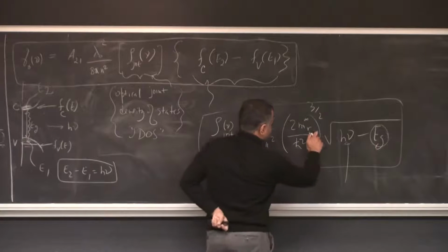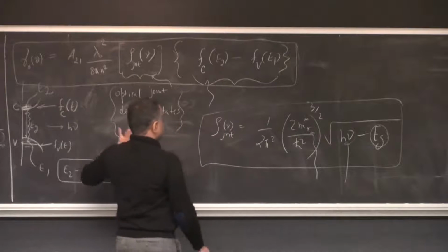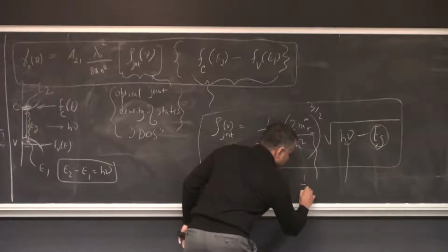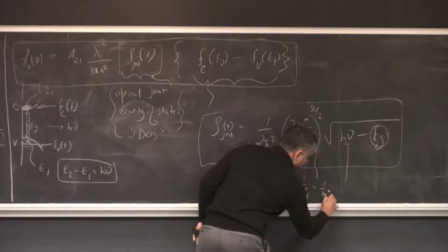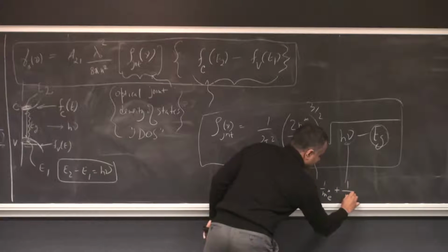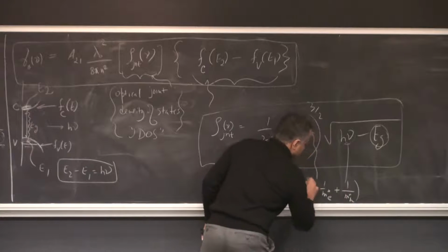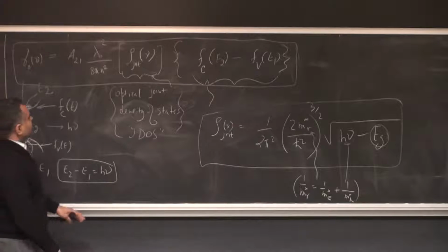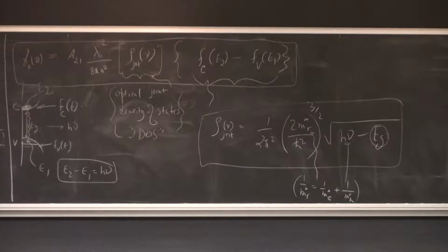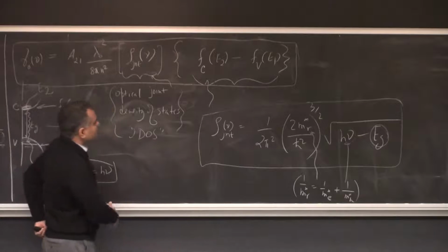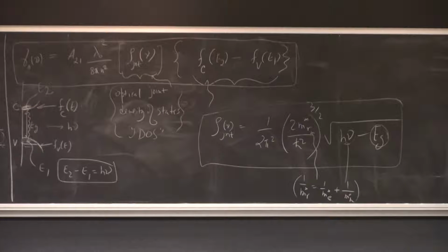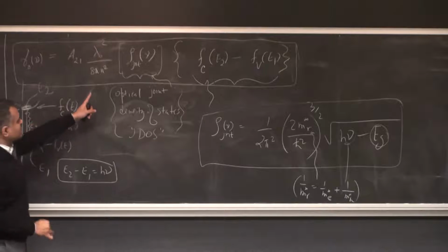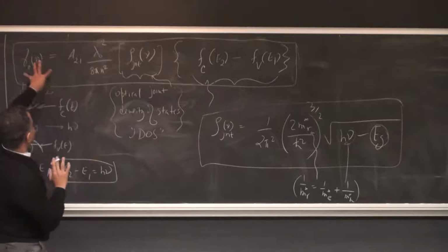There is a reduced mass. So this is a reduced effective mass, meaning the reduced mass is going to have the information of electrons in the conduction band and electrons in the valence band. I'm going to explain these things today. Anyway, every time I look at this expression, I really think it's a very interesting, very beautiful equation. It has so much of some of the biggest findings in the last century of quantum mechanics and thermodynamics buried inside this. And this is the gain spectrum.